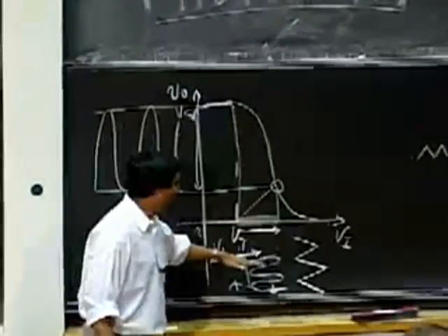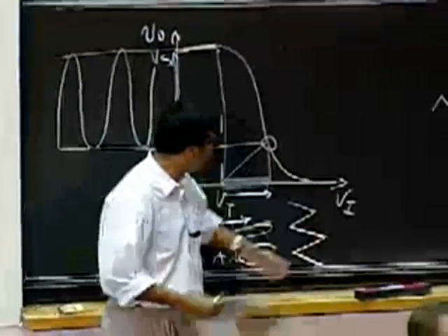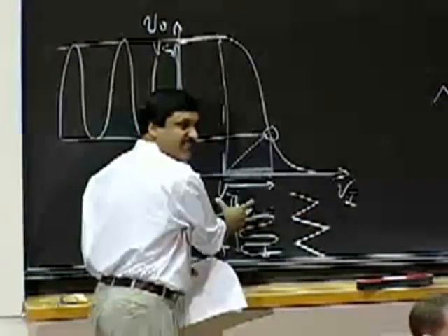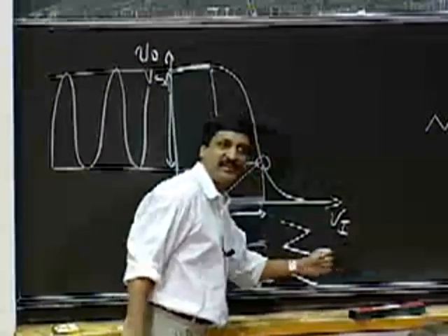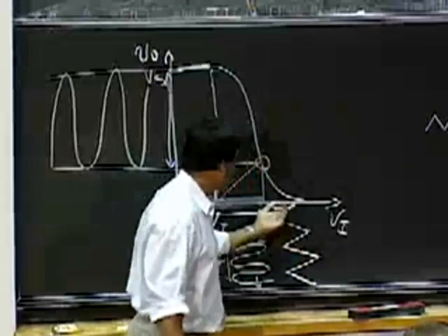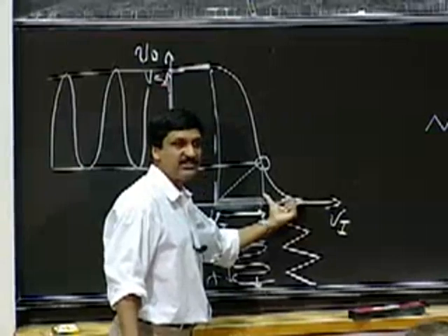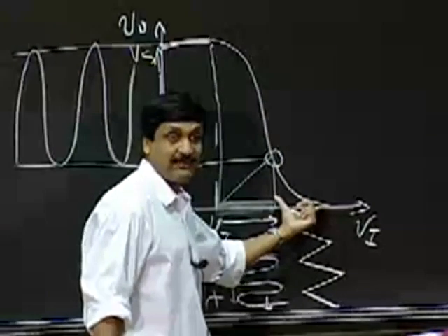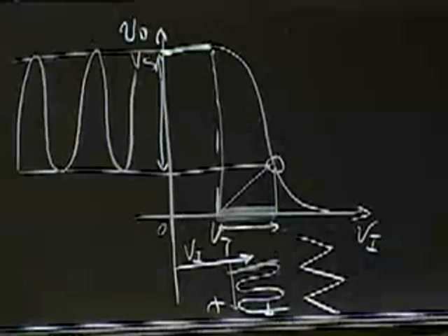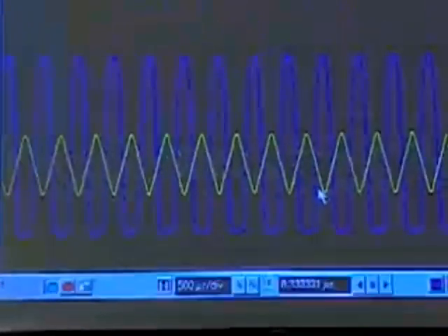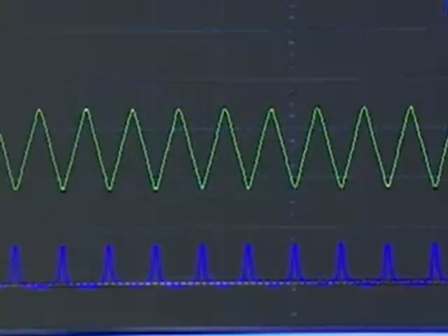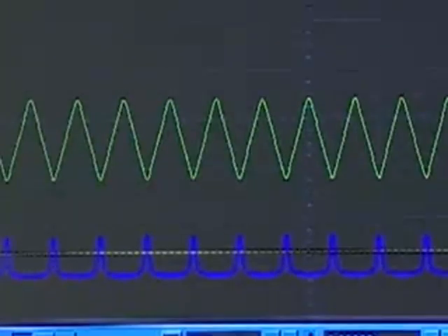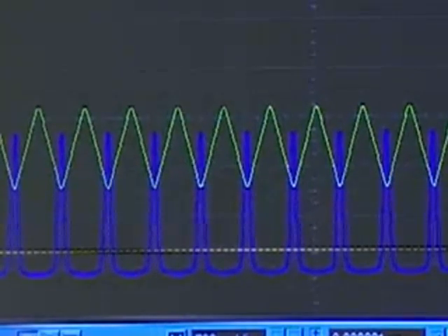What I'll do now is apply an even higher offset so that this triangular wave begins to move here. Okay, if I apply a very high offset, what I'm doing is overdriving the amplifier, boosting it so high that the MOSFET is going to go into its triode region, and you're going to see that I won't have any gain. Okay, my output is going to shrink noticeably if I overdrive the input. So you'll notice the input going higher and higher. I'm going to pull the trigger point down. There you go.